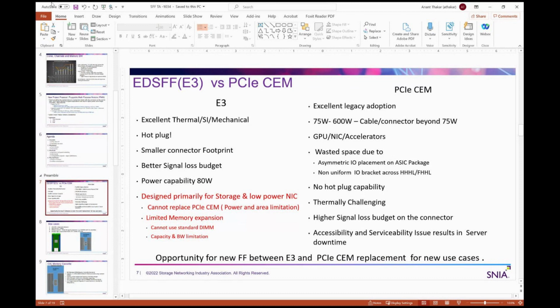Yeah, because the more capacity you try to add onto this, the DRAM chip densities change every 2 years with the node, correct? And when the node changes, you are going from 24 gig to 48 gig. That will happen on every 2 year generation, and you will be able to generate more and more capacity. The challenge is that the moment you do that, the power also goes up big time. A 16 chip solution on the E3 is extremely difficult to pull off.